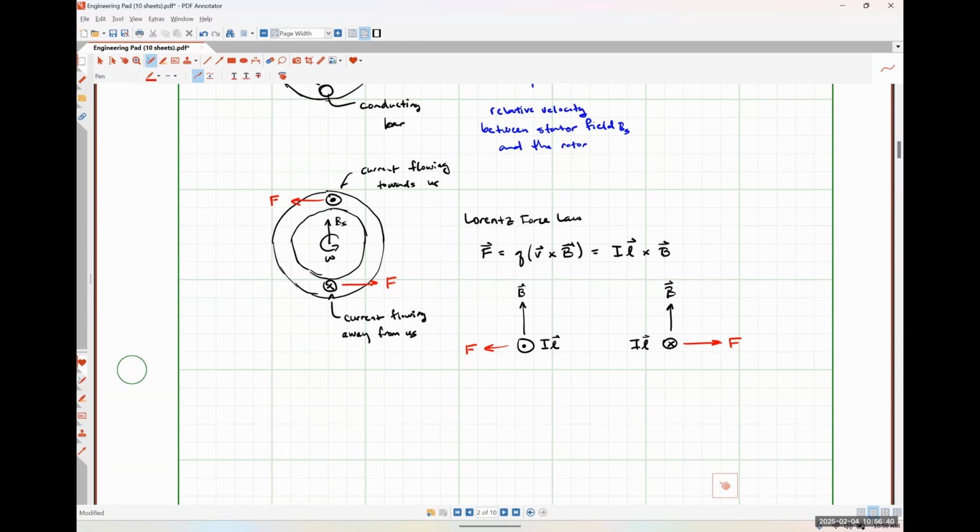Now, what's the limit on how fast the rotor can spin? Well, we know that the absolute maximum speed that it could ever reach would be omega, right? If all we're supplying is an electric signal that's oscillating at omega, we're never going to cause the rotor to spin faster than omega because we're not putting in any extra energy that will make that happen.